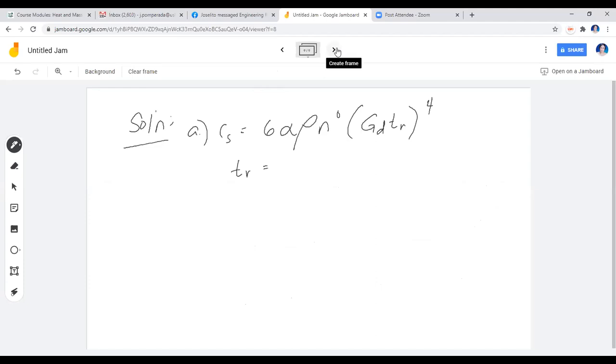So in this case, we will have your 4 cubic meters. We divide that by 0.00017 cubic meter per second. Okay, so this will give us a drawdown time, or a residence time, of 23,530 seconds. And now everything is just a matter of substitution to the formula.